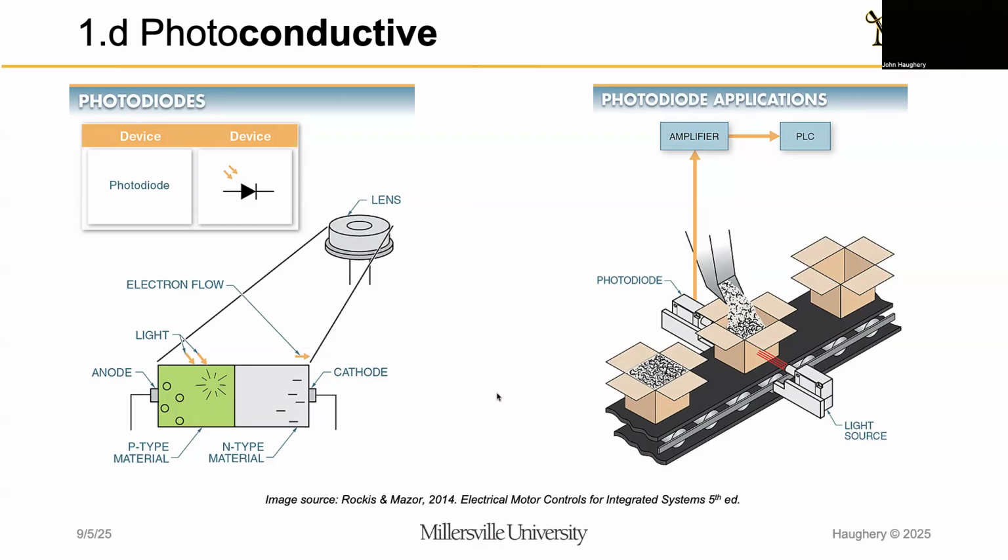And so we oftentimes use this in laser-based sensors where we have a laser beam across a conveyor belt, and once the laser beam is broken, it knows to fill the box with packing material. Typically, this has an amplifier circuit that's beyond this class, but it's not going to have any moving parts, right? The key point for us here is we're using diodes and semiconductors in our circuitry of our sensors so that we're not using mechanical contacts with coils.